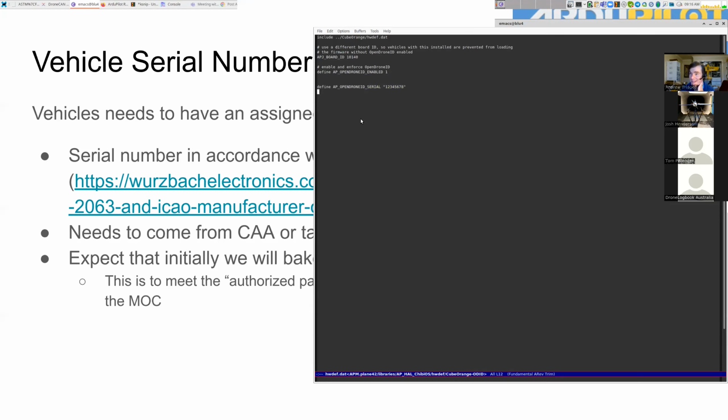So is the idea, look, that one option will be ID and then it's defining the HWDEF, but I expect the most common mechanism will be to bake it into the firmware for this device, right? Your transmitter module. Okay. So that when you ship the transmitter module, it will have an ID baked into it.